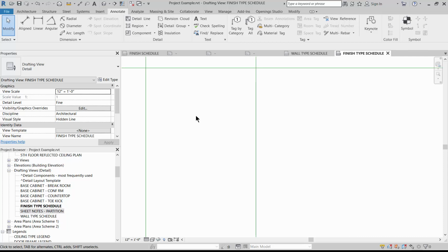One for floor finishes, one for wall finishes, and then finally one for casework, millwork, or anything that's not really a floor or a wall finish. So 3 shapes. If you want to create a couple of additional ones for miscellaneous things, that's fine. Ceilings, we are denoting through hatch patterns, so you would be relating that to a particular hatch pattern, and it wouldn't necessarily have a symbol on a ceiling, although sometimes we do that as well. So that's a possibility. You could create one for ceilings.